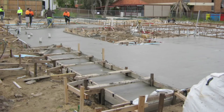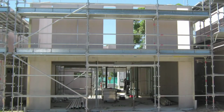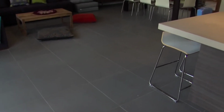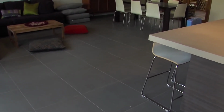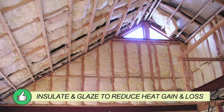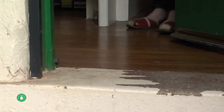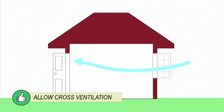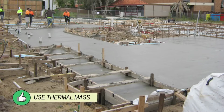A concrete slab or internal masonry walls are the easiest ways to provide effective thermal mass. A slab on the ground takes advantage of the Earth's mass to even out indoor temperatures throughout the year. So, to design and build a comfortable home, insulate to reduce heat gain and loss, use seals to prevent drafts, provide openings for cross ventilation, and use mass to even out the temperatures. As you can see, it doesn't have to cost more to build a lower energy home, just a little bit of know-how.